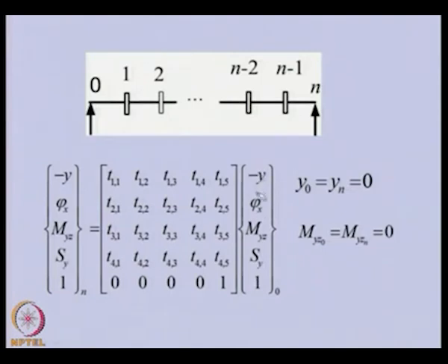and if there is unbalance in the system, the form of the overall transfer matrix will be this. So, the last row will be 0, 0, 1. These correspond to the unbalanced force. Other terms are multiplications of various point matrices and field matrices, and basically all these will be functions of omega, which is the spin speed of the shaft for forced vibration. For free vibration these terms will be 0, and omega we can take as the natural frequency of the system.